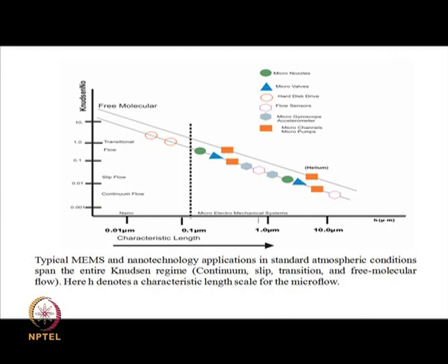But the moment you go beyond 0.01 and up to 0.1, the properties will still remain the same, but you have to assume slip flow at the solid fluid interface. That is known as the slip flow regime. If you go beyond that, for Knudsen number greater than 10, the motion of the species present can be interpreted as free molecular flow, and in between 0.1 and 10 you have a transition where the flow changes from slip flow, with properties still the same, to free molecular flow, where the properties are also going to vary with position and time. Somewhere in between you have transition flow.